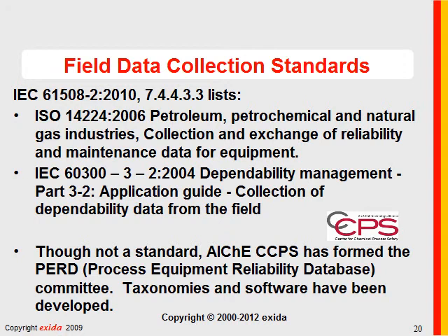As you begin to thoroughly understand these field data collection systems, of course, one can refer to standards that have been written. The 2010 version of IEC 61508 specifically lists ISO 14224 and IEC 60300-3-2, standards or application guides at least, on collection of field failure data.